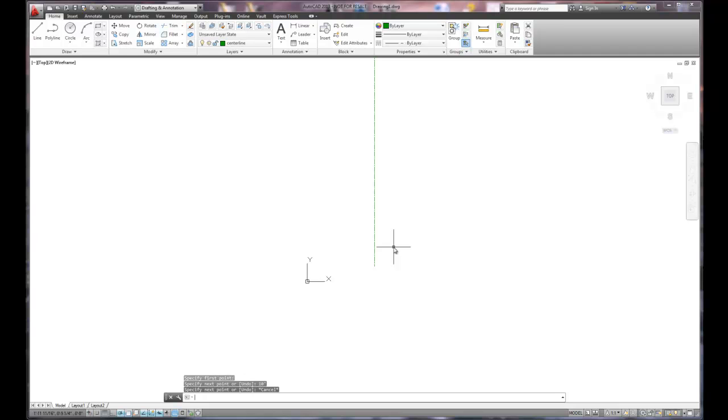There's two ways to do that. You can double click on the wheel of the mouse very quickly, and that is going to invoke a zoom extents. The zoom extents command will magnify the line to fill your screen. The other way to do that is to come over to the right hand side and use the zoom extents button. Both will work. It's whatever you feel comfortable using.